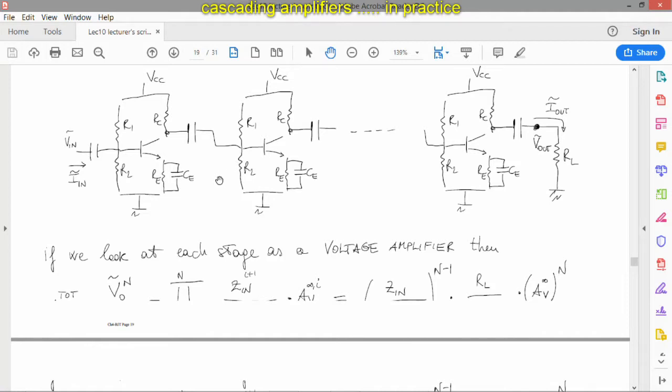The capacitor is important because it decouples the DC component. So each stage is effectively independent from the other. That's the nice part of C-coupling. Each stage you've studied on its own, you've defined it, and then you take it and you copy and paste it.